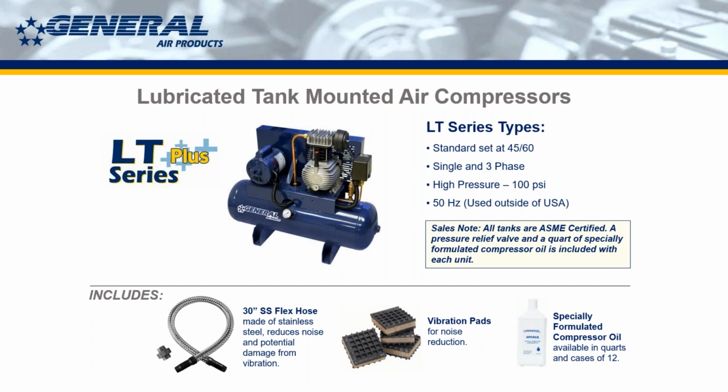Something else to keep in mind at installation when you put a new one in. You may see in the oil gauge there, in the sight glass, a little bit of oil in there. We put a very small amount of oil in order to test run these units, but that is not enough oil to run the unit long term. That's why we include oil with it. So you must add oil when you get these, even if you see a little bit in there. It's not enough to start it.